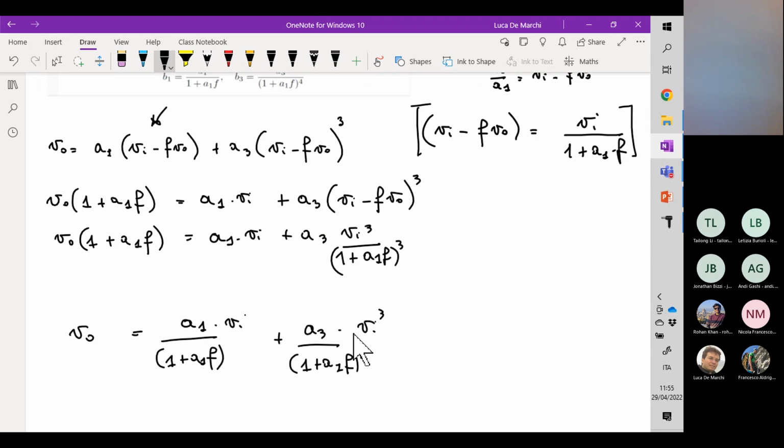If we further reduce the DC gain, we may get in trouble. For the second configuration, the loop gain is null in this specific point, which means that the phase curve is below the minus 180-degree curve, and therefore the phase margin is negative.